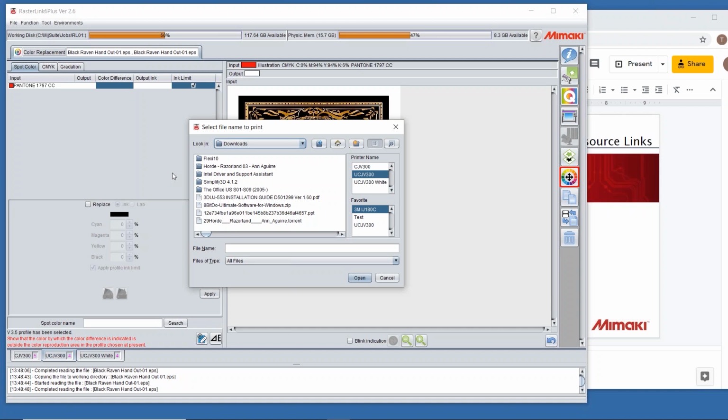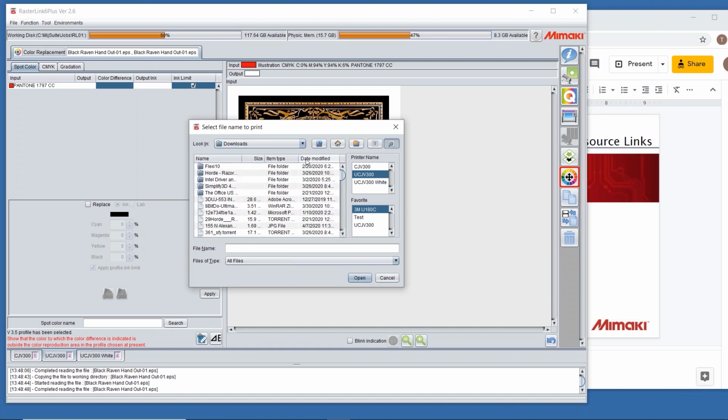A lot of it depends on blade condition. If you have a magnifying glass, take a look at the very tip of the blade and make sure it comes to an absolute corner. If it looks ragged, the blade is probably broken and will not corner well. And then the last step you can do is what Hugo was mentioning. We do have a function called overcut, where it takes every line in the vector image and cuts it slightly longer than intended, 1 or 2/10 of a millimeter, so that it's easier to remove the piece. Sometimes we'll use that if we're doing sans serif fonts or anything with a lot of curves to it that come to really sharp corners. Those can be difficult to pull out. Those would be the main tips that I'd look at.